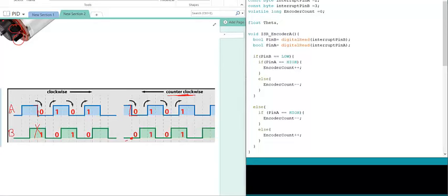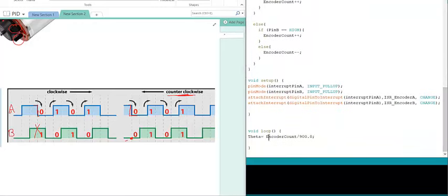So there's a float variable data, and we also need a data previous value. We'll use that to calculate RPM. So the encoder count is divided by 900, and 900 is just the value for counts per revolution. That's the total count in one revolution, and the encoder count just gets divided by that, so we get the true angular position.